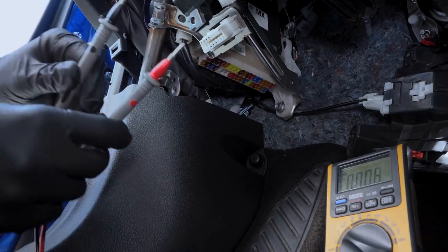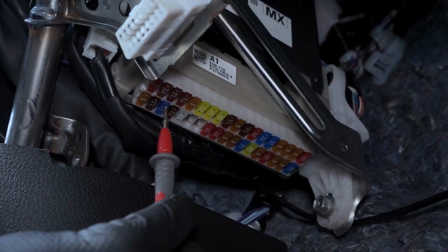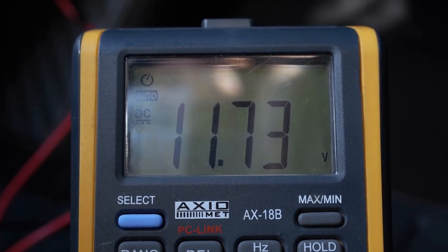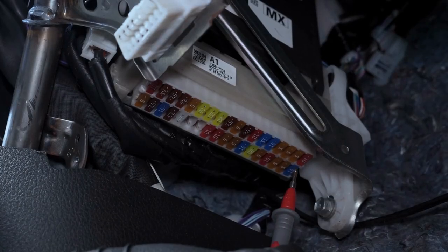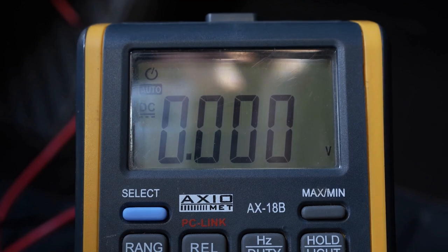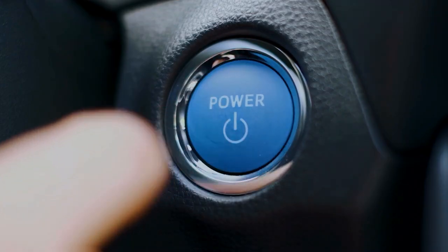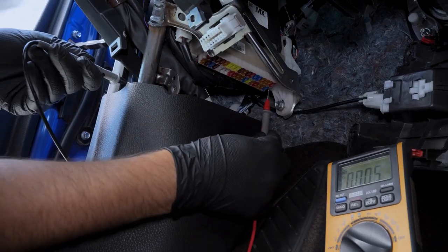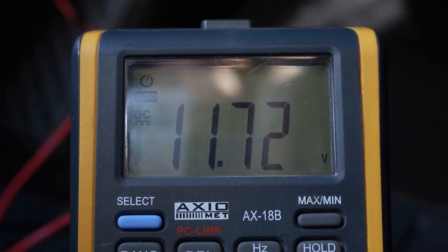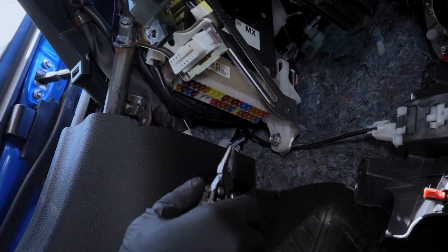Connect the negative multimeter probe to the vehicle's frame, which acts as a ground. Connect the positive terminal wires to a circuit point where the voltage reads about 12 volts with the vehicle's ignition off. Find the connection point for the ignition cable, digital input 1, where the voltage is 0 volts when the vehicle's ignition is off. Turn on the ignition. Now, the voltage at the ignition wire connection point should be 12 volts. Use standard pliers to remove fuses from the fuse box.